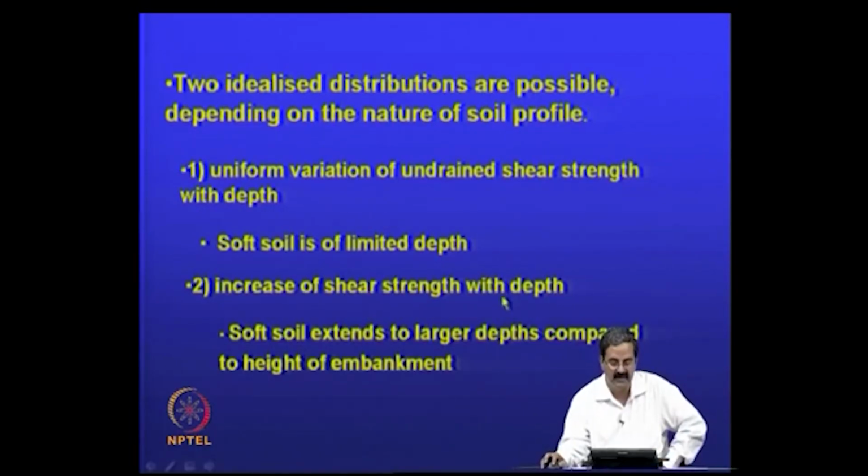That information is quite important when you do the analysis, whether it is based on limited depth or unlimited depth, because the failure surfaces keep on searching, and since the shear strength increases with depth, it will have a higher factor of safety.